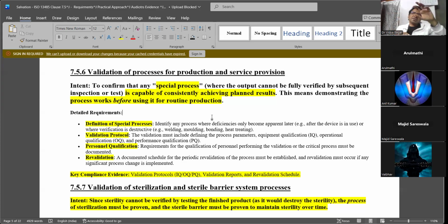There will be a lot of variables: heat, temperature, process run time. All this I'll adjust. I'll keep one as a variable and the other as a constant. Then in the second experiment, I keep the other variable constant and the two will be changing. We keep experimenting till we get a consistent 0.2 mm inner diameter tubing. So we'll run almost 100 or 200 samples. Again, it depends upon the sample size. Once you run and check them, you check whether you're getting 0.2 mm ID with your process parameters.